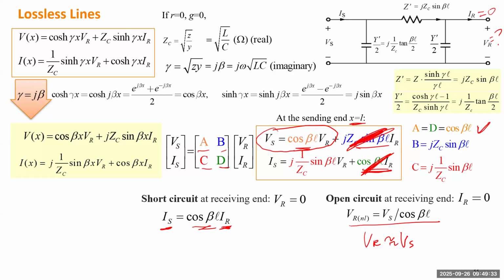So for the first contingency, we expect the factor to be really small, so that even if you have a short circuit on the load, the source is not impacted. But for the second contingency, we hope this factor to be large, close to 1, such that the load voltage can be maintained at the same voltage as the source voltage. So let's try a different value.